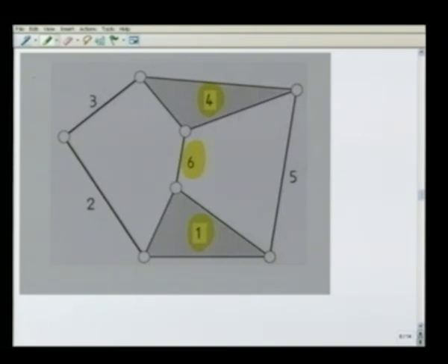So here we have two ternary links 1 and 4 which are connected via binary link 6, binary link 5 and by two binary links, namely 2 and 3. And this particular chain where the two ternary links are not directly connected is known as Stephenson's chain.